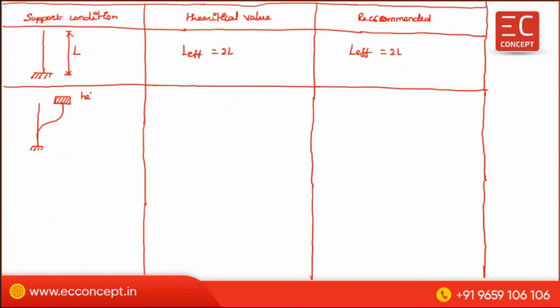Here rotation is 0, so this end is held against rotation, not held against translation. Then L effective theoretically is equal to L. Here the recommended L effective is 1.2 L. Be careful, recommended is 1.2 L.